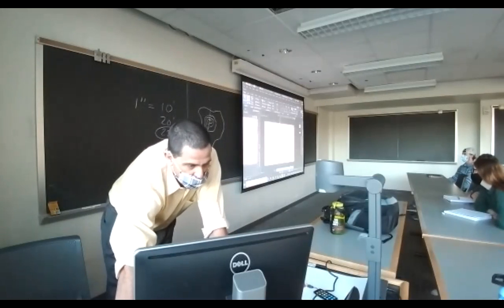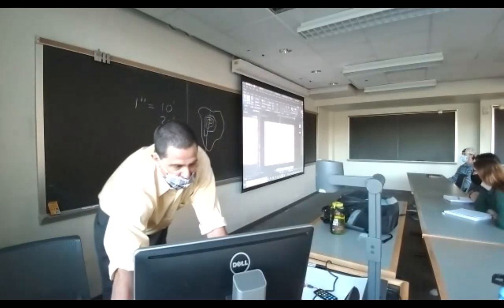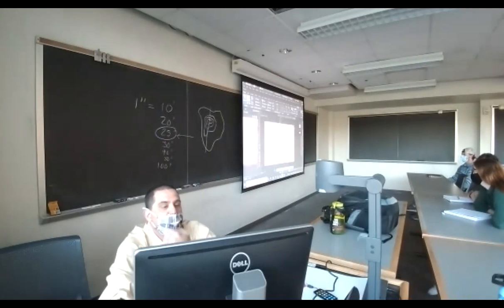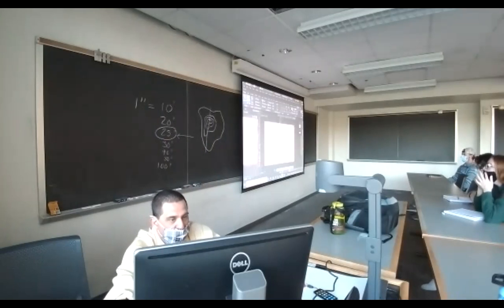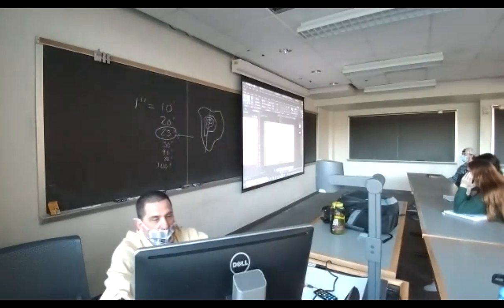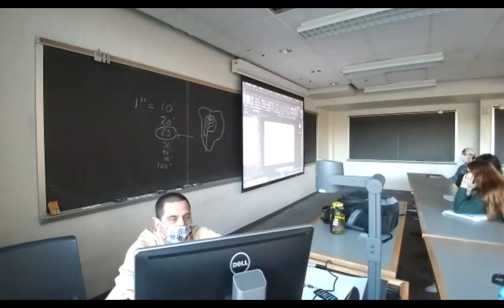Okay. Here's where I want to change stuff. Your default point style is set to basic and elevation and description. And your next point number really should be 2.